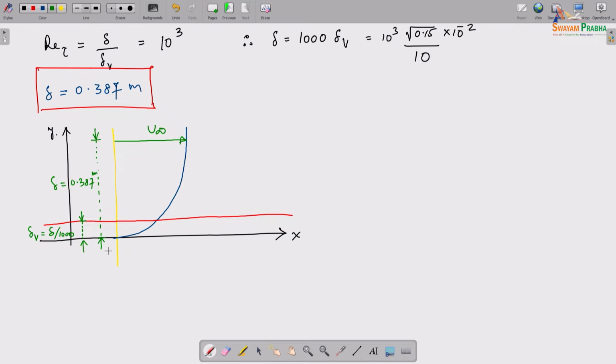So the thing was that at high Reynolds number, close to the wall, there is an inner layer in which the mean velocity profile is determined by viscous scales, independent of boundary layer thickness and free stream velocity. This is Prandtl in 1925. This is the law of the wall.